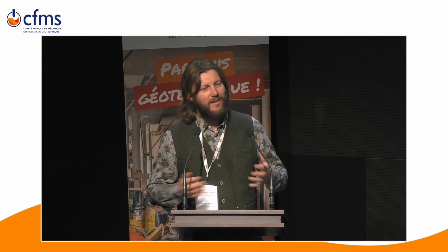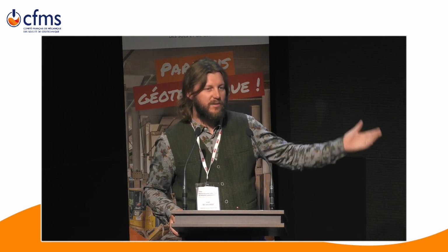So the question was, in my opinion, more important for the design of the facing, because with the initial tension we got, you ended up with very stiff facing. I find it also a problem to have very stiff structures, because soil nail walls are quite soft. It's a good way to resist earthquakes, and I think it's a shame to over-design the facing or even the length of the nails. So the main question was actually regarding the facing design, and for the stability of the wall.